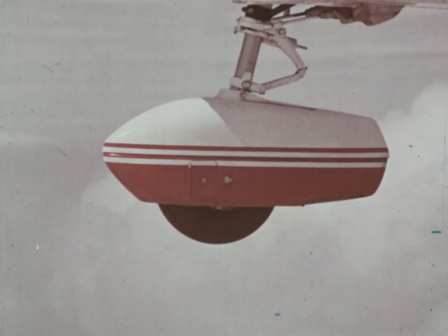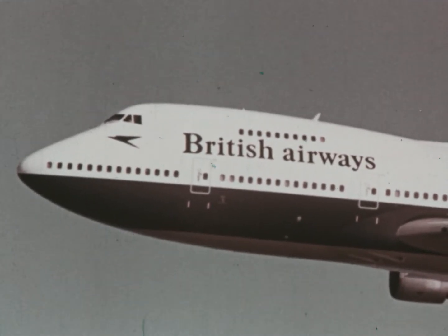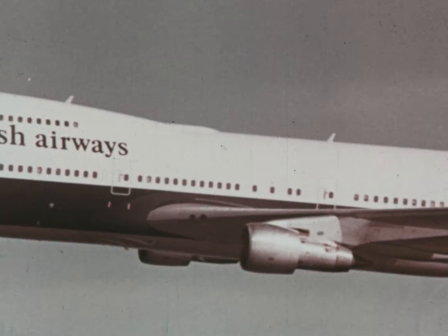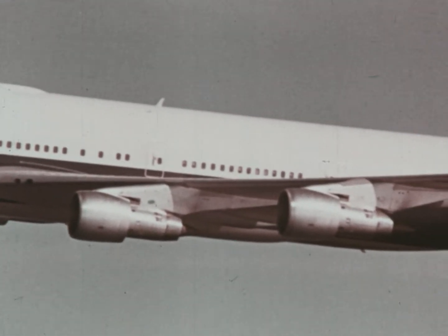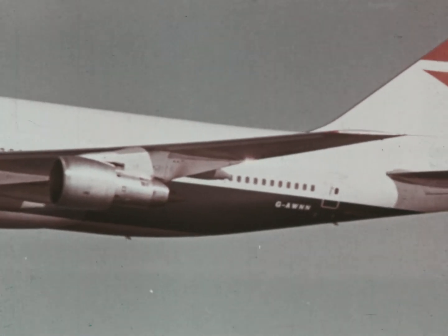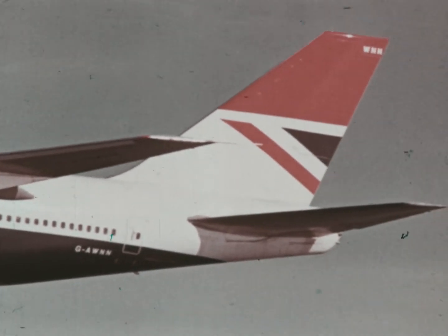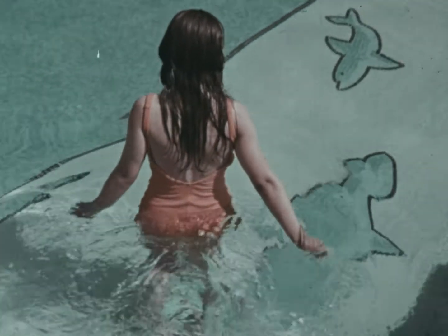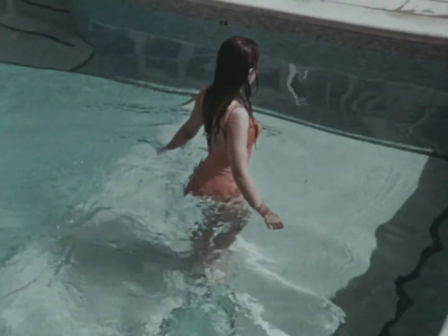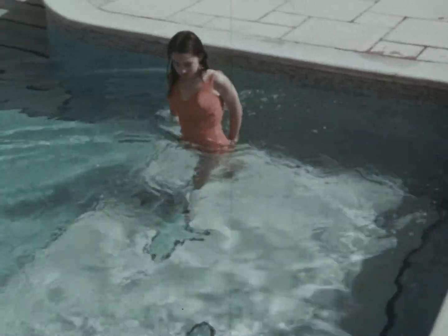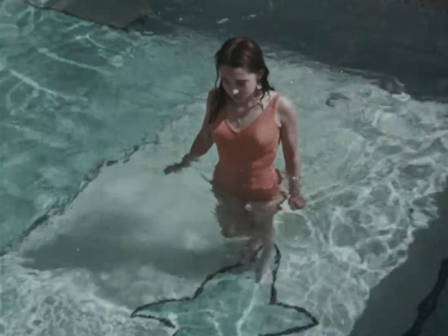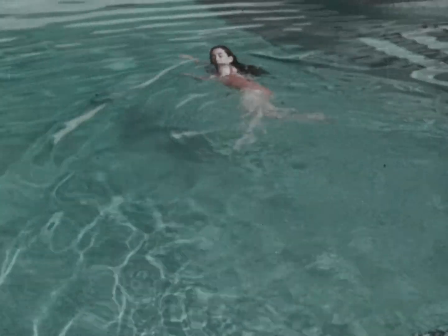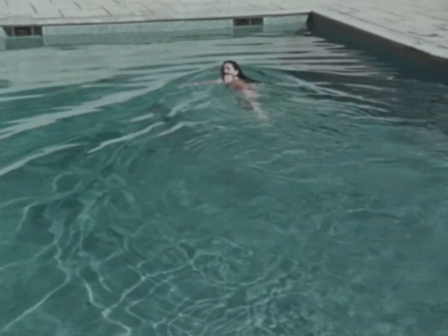Another kind of drag that also increases with speed is that of skin friction or surface friction. This is caused by molecules of air clinging to the whole surface area and combining with pressure drag to hold the airplane back. We experience both these forms of drag in water. As we move about, we can feel the pressure resisting us. And at the same time, the water molecules in contact with our skin tend to move with us and try to pull the surrounding water along with them. Even when we streamline ourselves and apply thrust, we can still feel the water clinging to us as we move.